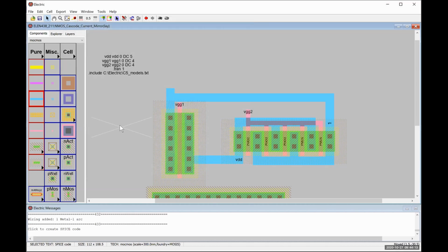Here's, I believe, properly set up spice code where I'm just applying DC voltages to all the pins, where ground is ground, so I don't need to specify what that one is. So I'm applying 4 volts to the gate of both of the transistors, 5 volts as my positive power supply voltage that I'm applying to the sources, because this is a PMOS, but in the grand scheme of things, it won't particularly matter. And I'm grounding the other one so that I can just measure current.